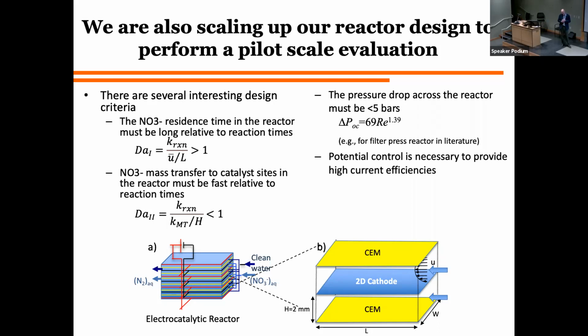So yes, one of the challenges with having parallel reactors is that they're sharing basically that same big chamber. And in our system, we brought a reference electrode in from the top, right? You can't really do that. You can't bring a reference electrode into the top. It'll only be a reference electrode for one cathodic chamber. You've got all these other ones that are down in the system that you don't have a reference electrode for. So how do you control the potential for that whole system? And that's a tricky issue.